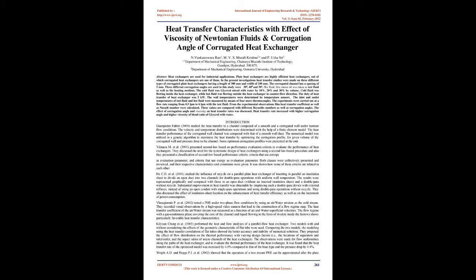The wall temperatures were determined by temperature sensors. The inlet and outlet temperatures of test fluid and hot fluid were measured by means of 4 more thermocouples. The experiments were carried out at a flow rate ranging from 0.5 lpm to 6 lpm with the test fluid. From the experimental observations, film heat transfer coefficient as well as Nusselt number were calculated.